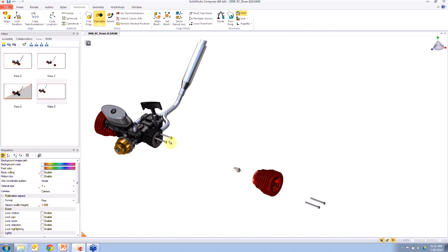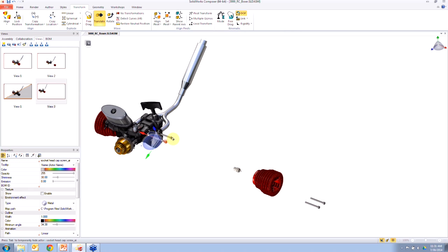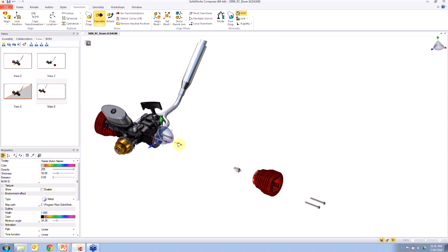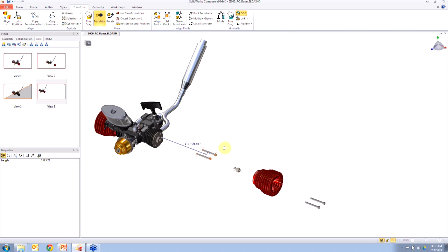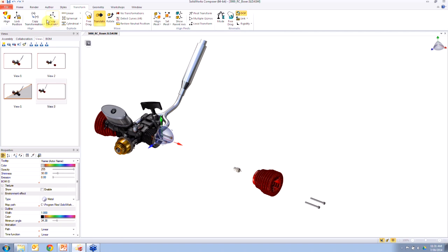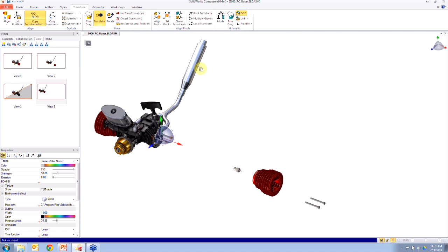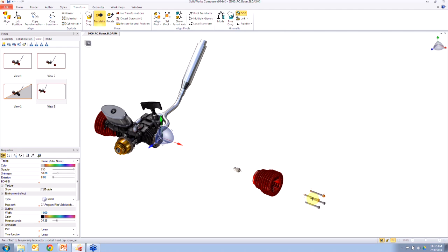Now, these 2 items here, I want to translate out exactly the same as those. So I'm going to select them, and if I try to eye them in, I probably won't get it perfect. So what I can do is go up here and click Copy Transformation, just mouse over the other ones, you'll see the ghosting there. They'll actually pop exactly where you want them to go. I click on that, and now I've moved them out the exact amount.